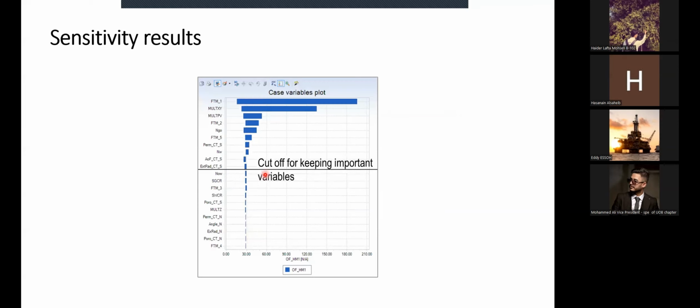And by the way, this curve or this graph, we call it a tornado plot. It looks like a tornado. That means it gives you either positive or negative impact. But the idea is, it is impacting. So you do what we call a cutoff, which is the next step. First step is you understand these parameters are impacting your reservoir. These parameters are not impacting, so you will ignore this one. You will not spend time on changing these values because it will not give you any impact. You spend time on adjusting and changing these parameters because your model is sensitive to that.